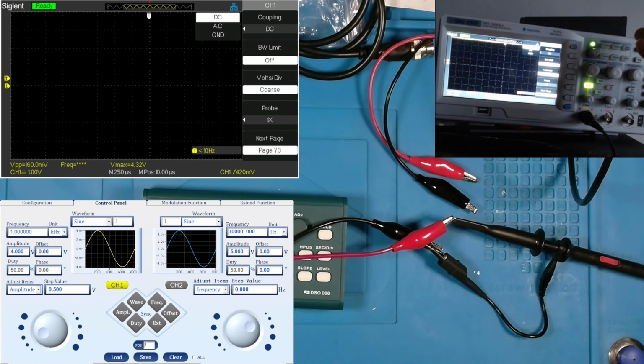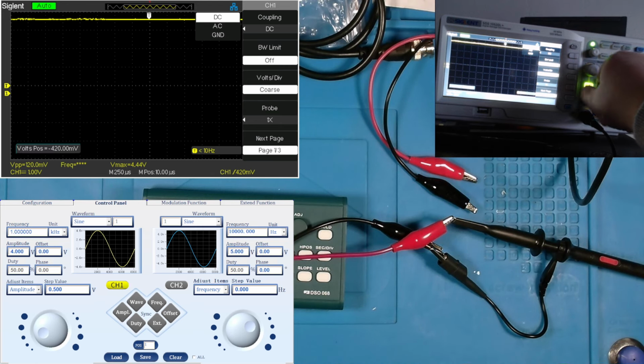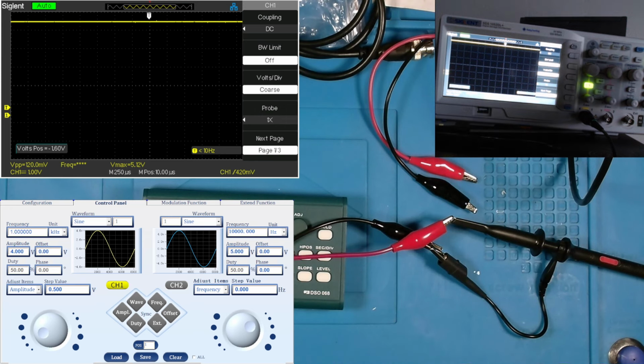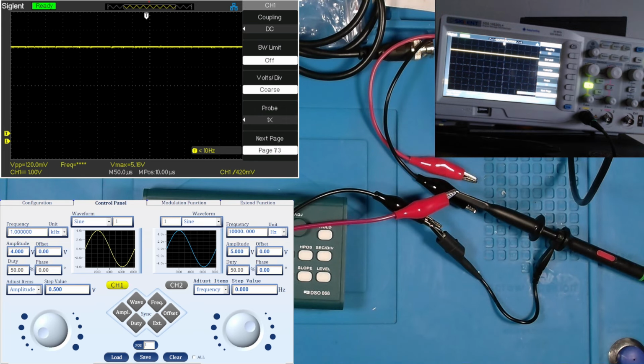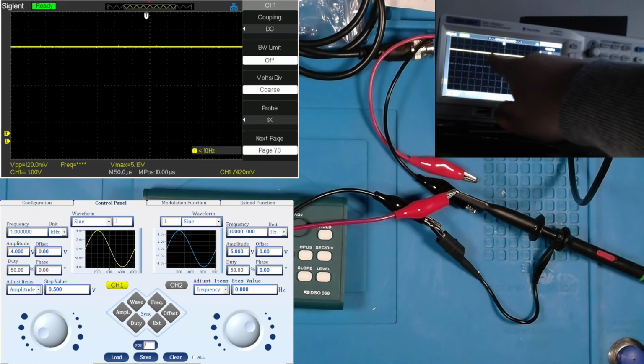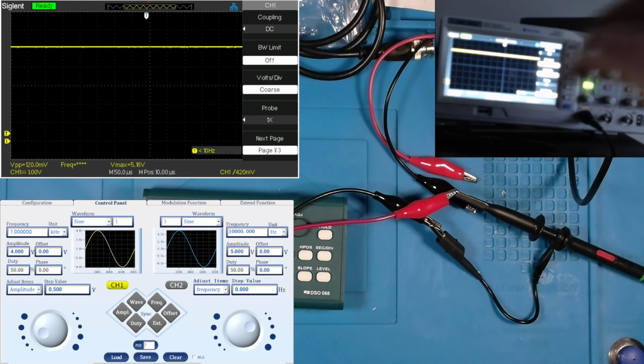Yeah, now it's above where I can see it, but I have to bring my reference down to be able to see that DC signal again. Well, when it comes to a DC signal, what am I actually looking for? Essentially that it's not dirty. I have a nice defined line here, and I'm not seeing any scraggly anything sitting within here.